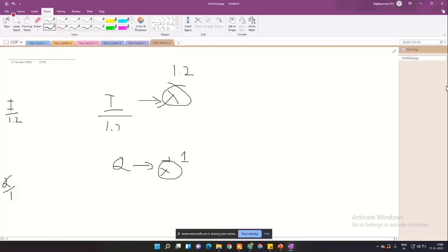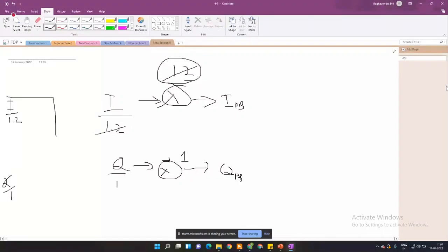Now in the mixer, the 1.2 division and the multiplied gain of 1.2 get cancelled, and my output at this point is an analog passband form of I. And over here this is the analog passband form of Q. So you see, I've gotten rid of the gain impairment by using the IQ impairment correction part. I've only shown you for gain. They do this for everything: quadrature skew, DC offset, anything that's present.